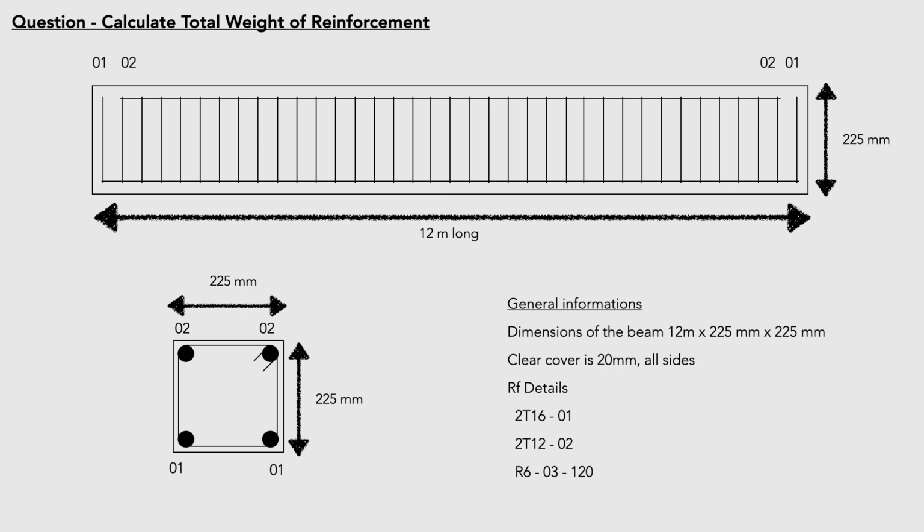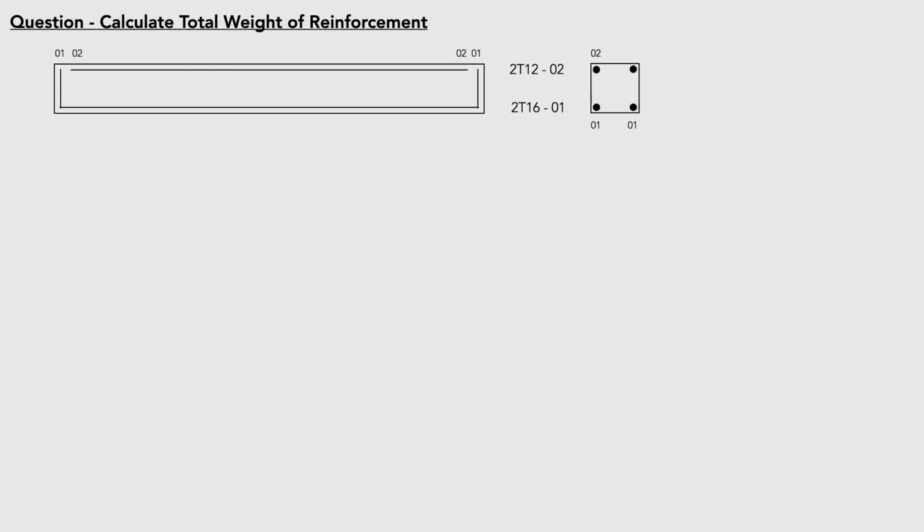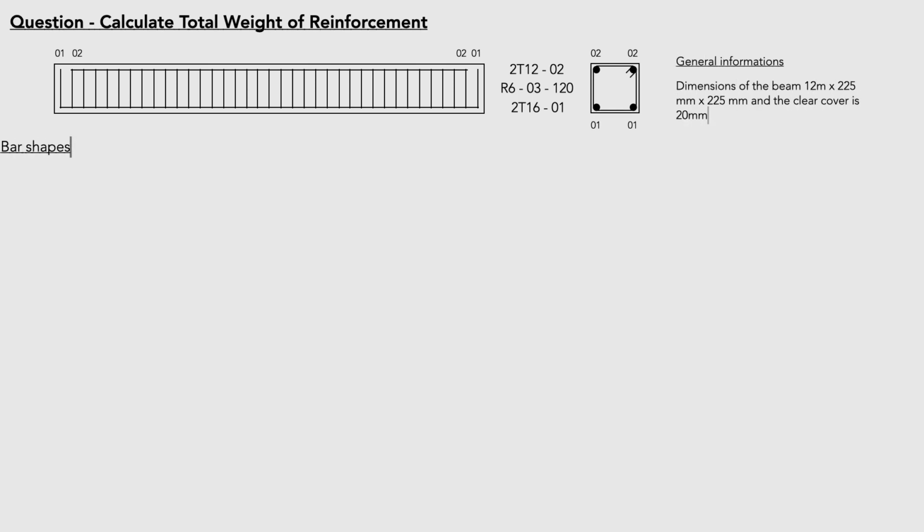Longitudinal section and cross-section are shown here for easy reference. The animation illustrates the layout of bars in both sections. Furthermore, the clear cover for all sides is 20 mm. Bar number 1, 2 and 3 consecutively have U-shape, linear and square shapes. The lengths of different bar shapes are identified using assigned notations, and they are P, Q, R, L, M and N irrespective of shape.